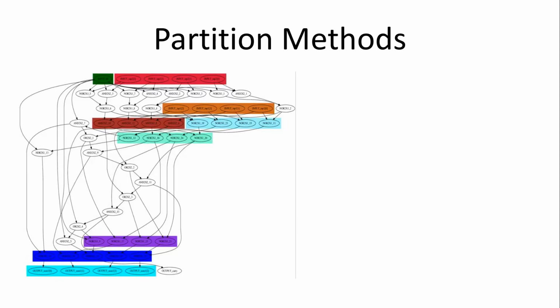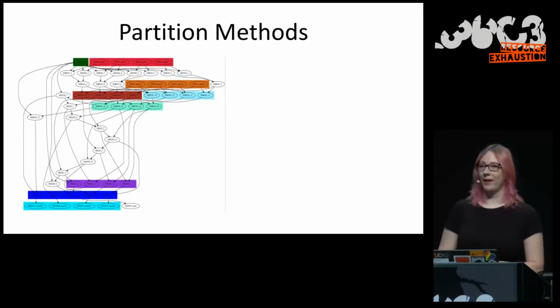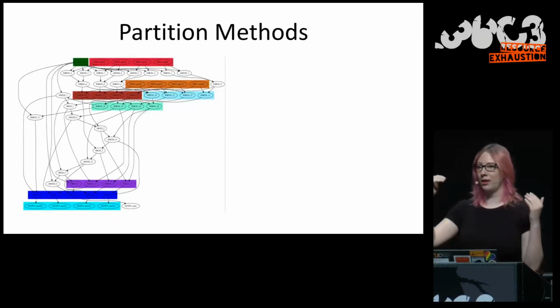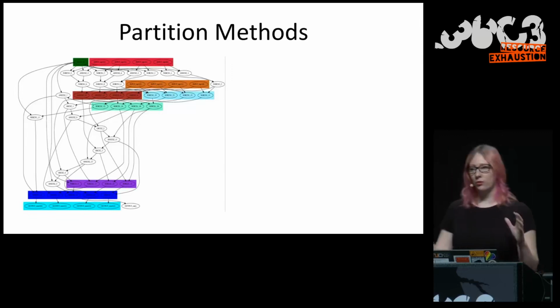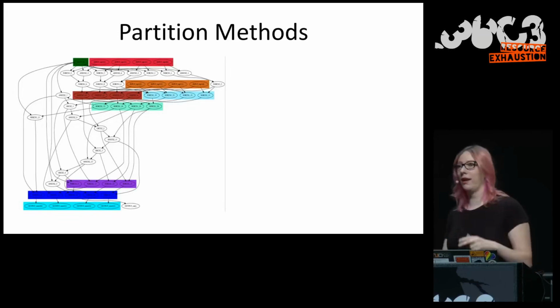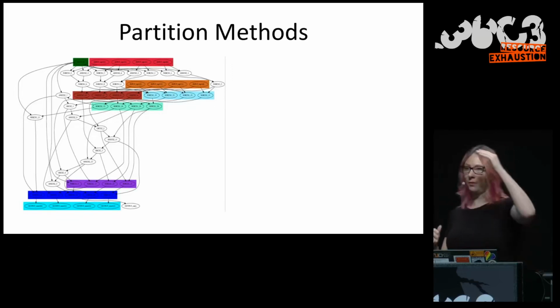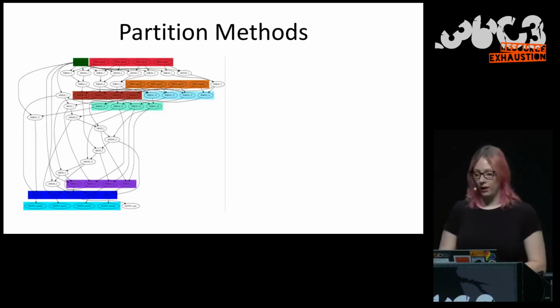And we can try to figure out where these words lie and then propagate them through the whole entire design, so we hopefully come from input to output. And then say, look, these are probably at the boundaries of modules. So in particular, when new words are starting to be combined in different ways, or maybe words are being split up, that's probably a new module. So if you go from your bus to your multiplier, all of a sudden you're now working on 32-bit architectures. You can say, look, beginning word, end word, everything in between is probably my module.